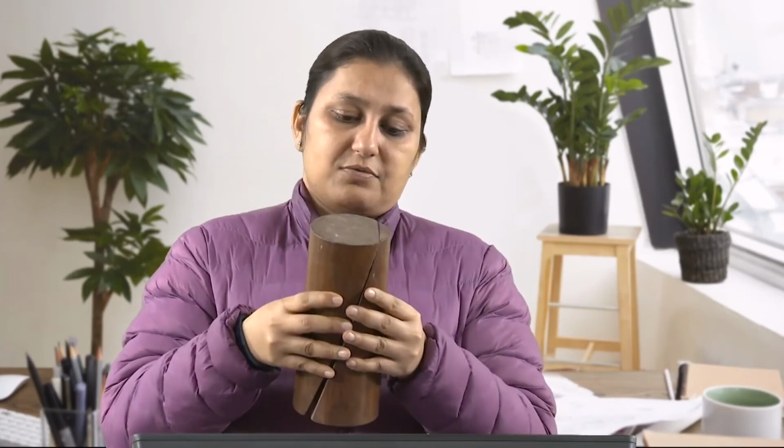This is part of the ellipse and here it is abruptly cut. So, we do not get a complete ellipse in this case. We get a distorted ellipse. It is not even an ellipse. It is suddenly truncated ellipse from the sides. This was dependent upon how the section plane was passing through the top base and the bottom base both. So, we have both the top bases and the bottom bases being cut, and that is why this peculiar shape.